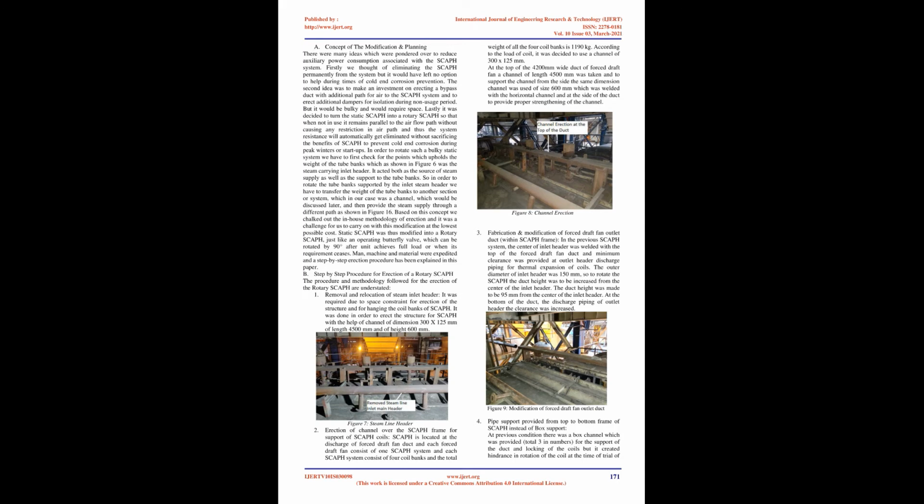SCAF design parameters and operational usage details. SCAF, steam coil air preheater, is equipment fitted between forced draft fans and air preheater to avoid the acid dew point condensation which occurs at the flue gas side in the air preheater due to the low temperature of the atmospheric air as stated earlier in the paper. The design parameters of SCAF at SPL are as follows. Number of SCAF assemblies, 02. Number of coils in one assembly, 04.